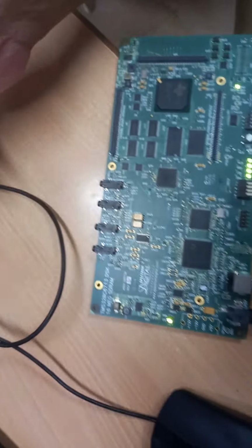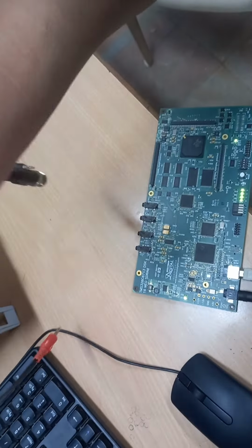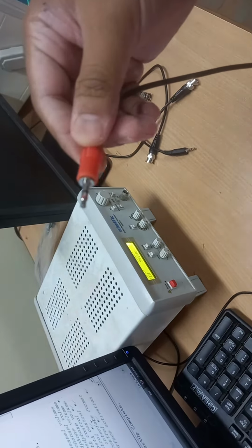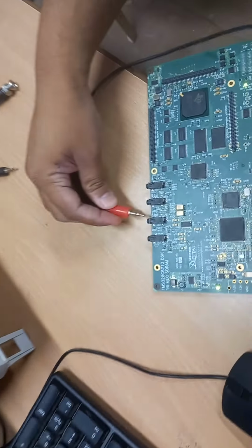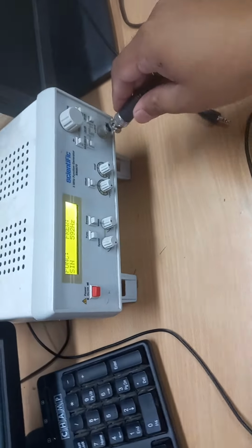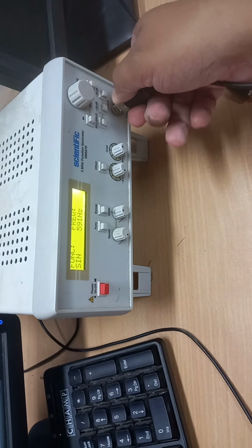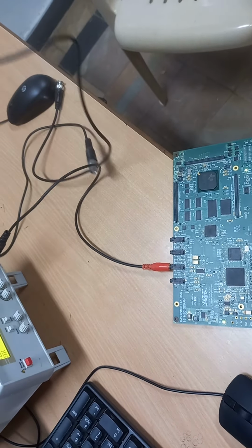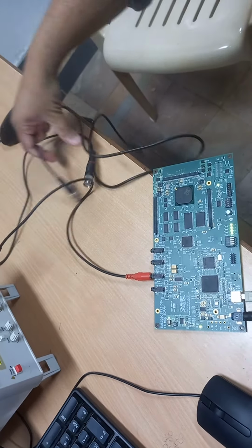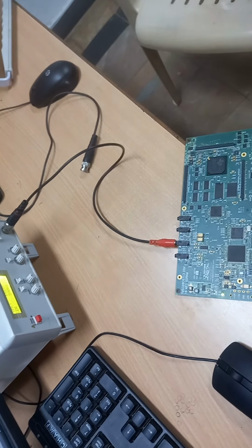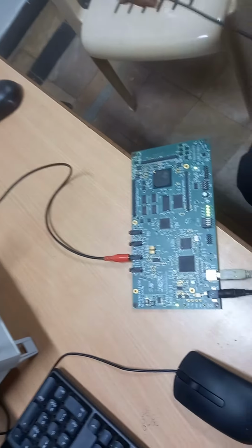There are 3.5 mm audio jacks already available in the lab. These are called 3.5 mm audio jacks. For this, the probe connection is made. What I am doing now is connecting this to the line in terminal of this particular DSP kit. The second one is the line in terminal, give it to the function generator. Next, one more 3.5 mm audio jack attached to the probe, that you need to give to the CRO. The third one is the line out.